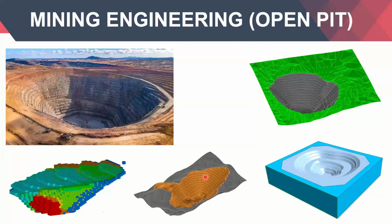That is, you just have to export the triangulated surface or the digitized surface from your block model and then import that into GTS. In that way, you can have multiple files for each stage of the mine throughout the life of mine where you can assess the factor of safety.